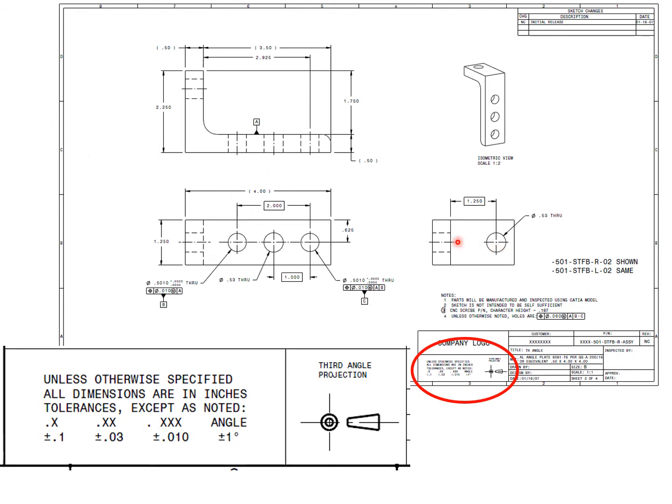So we have front view, side view, top view. One of the mistakes I see right off the bat is, notice how this leader is floating upward. I should have done the same thing with these other leaders here. Should have had them floating upward. And yes, it would have probably been crowded by these dimensions, so that's one excuse I can use. The reason they're floating downward is because these were in the way. But if possible, move them upward. It's still correct if you leave them the way it is.